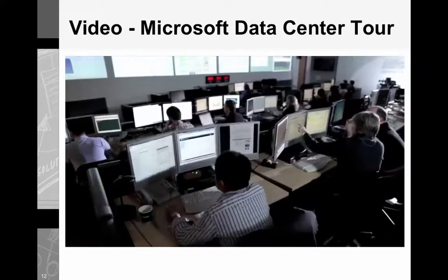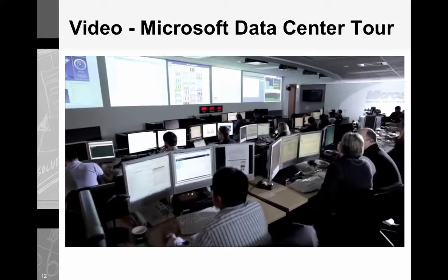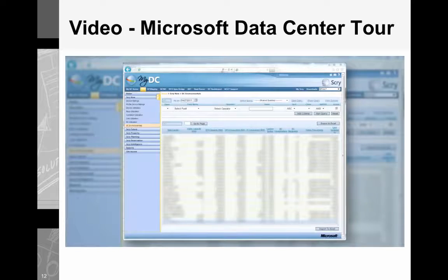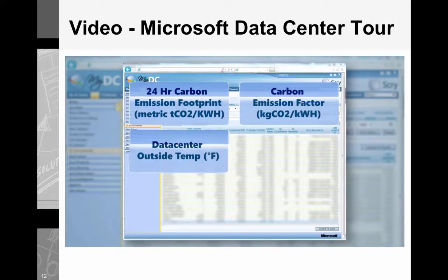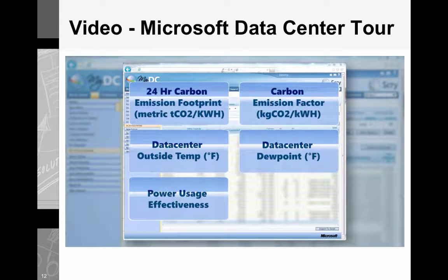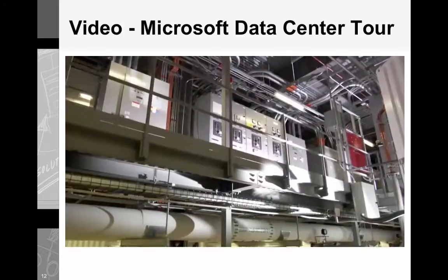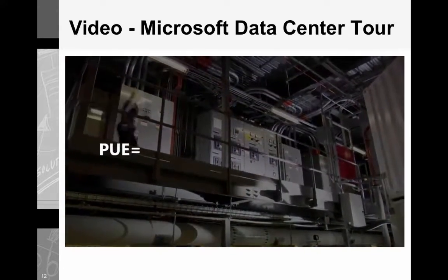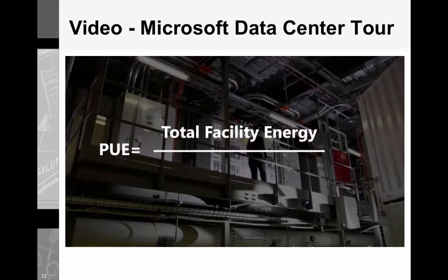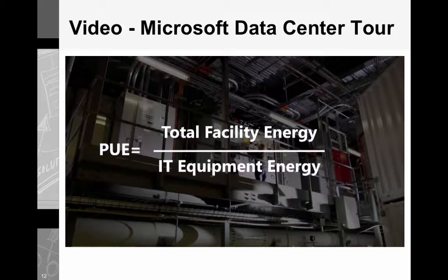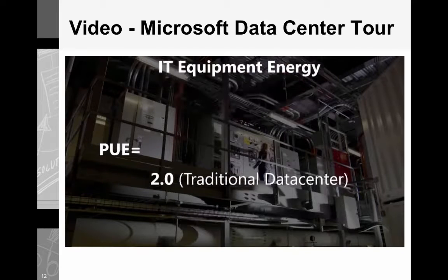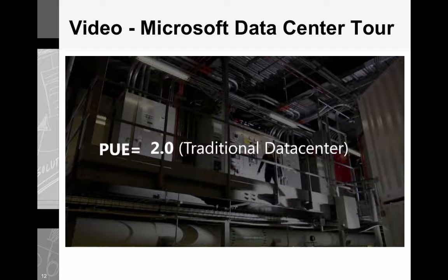We also deploy one of the largest implementations of Microsoft System Center in the world, and we use our own data repository called Scry to record power consumption and allow precise cost allocation to our internal business groups. Power Usage Effectiveness, or PUE, is the measure of total data center power consumption divided by IT, or critical power, and highlights how much power is consumed by supporting infrastructure versus the power to operate servers. A typical industry data center has a PUE of approximately 2.0, where the amount of energy consumed for the facilities and supporting infrastructure equals the energy to power the servers.